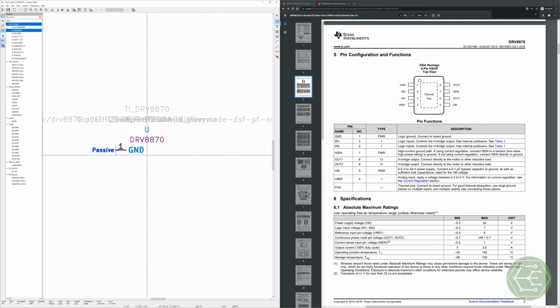Enough said. Okay, and this is my favorite shortcut, so pay attention. Insert gives you another pin spaced exactly correctly underneath it that copies everything and auto numbers where that makes sense. If you hit E, this is why I love doing this in KiCad. It has so many shortcuts. I've seen tools where this is like click, click, click, click, click. I hate clicking. I have tendinitis. Clicking sucks. Keyboard shortcuts are a lot easier on my wrists.